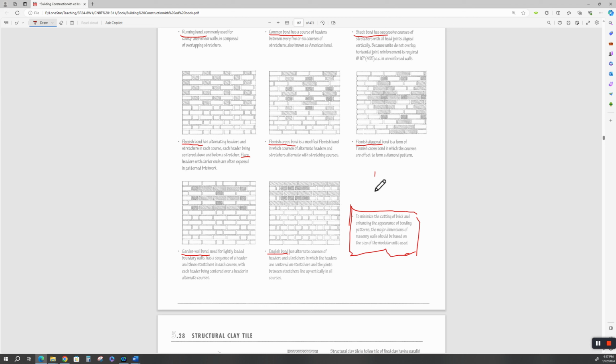It's just like a 4x8 foot sheet of plywood, right? That's the normal for the sheetrock or plywood or decking. Then your layout should be on that module, 4x8. So whatever masonry you're going to get, if you decide to use Billy Bob's masonry company, you get with Billy Bob and find out what his true dimensions are for the block.